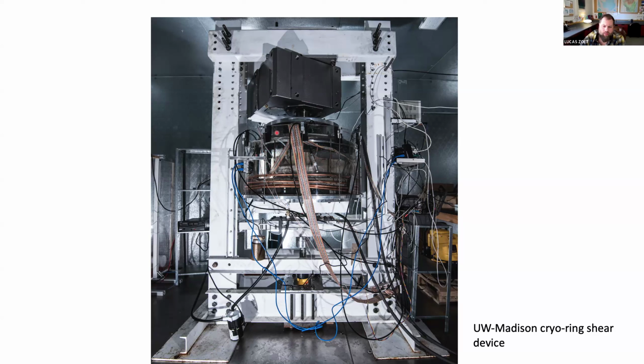And when we do that, we measure the resistance the bed provides to sliding at these different speeds. And then we'll increase the speed and do it again, increase the speed and do it again, or increase the pressure and do it again. And we can systematically step through changes in basically pressure, confining pressure, how we're holding the system together, or sliding speeds. And we can even drive the thing in a stress controlled mode.